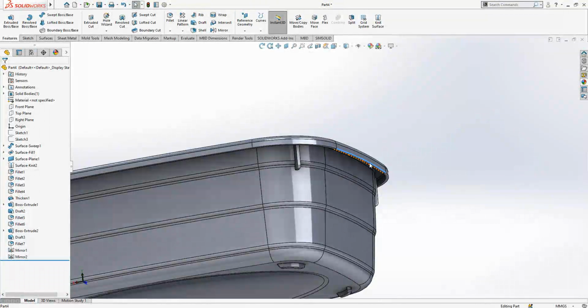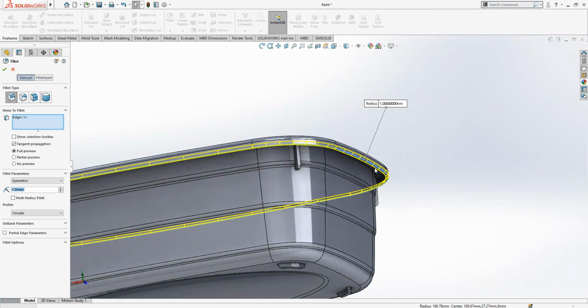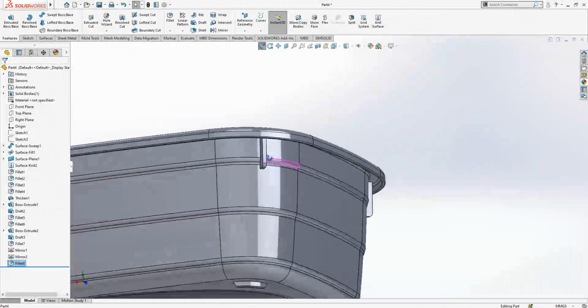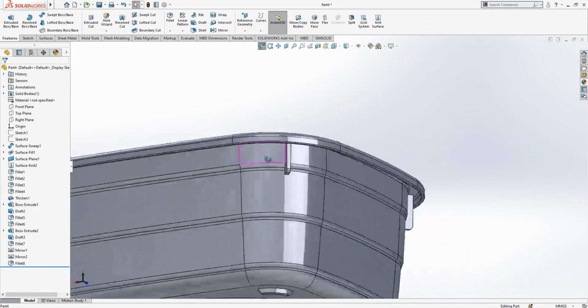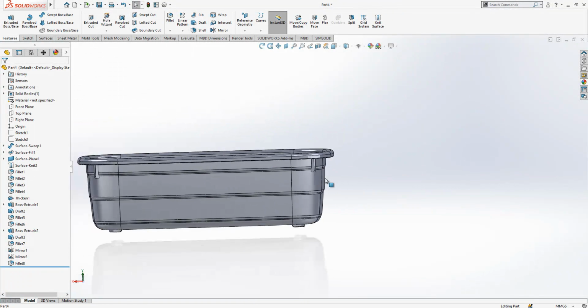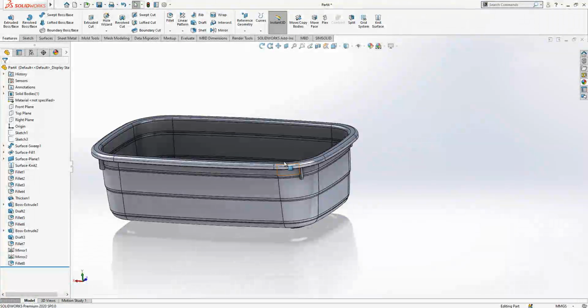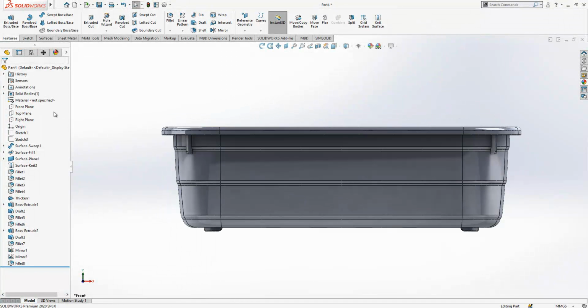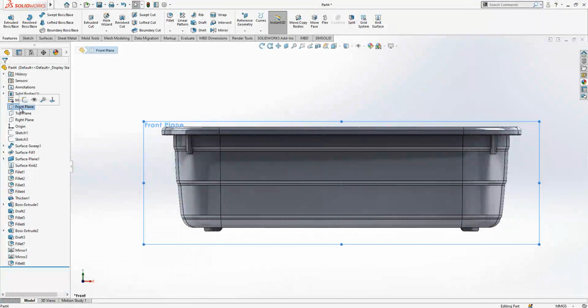And of course we will have little radiuses here as well, which will be 0.25. So big, and then I will complete. You can create radiuses here as well, but the radiuses will be determined, I think, most of the time by your minimal tool size. You should discuss with your mold producer. You can't do everything you want because there are some limits due to the nature of the production method. So I talk a lot, I will stop and work.